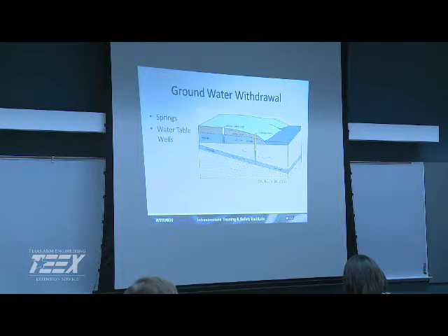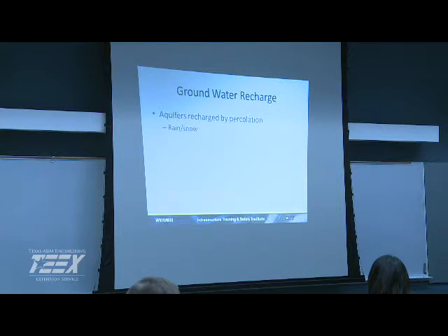So we look at our springs. We can have natural springs float up out of the ground. Then we have our water table aquifers, and then we have our artesians. Artesians are under pressure. So we're going to get it through percolation, especially on our shallow water aquifers. It's going to actually go down through the soil. Big one is coming out of, we just talked about lakes and all, rivers. So bank storage is a big component of our actual capacity of a river. And that's why alluvial aquifers close to rivers can be very beneficial. It can also be under the influence. It can be a GUDI, a groundwater under the influence of surface water. So we have to be careful in our proximity.